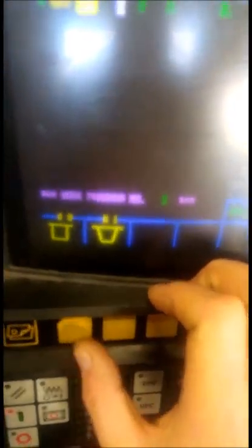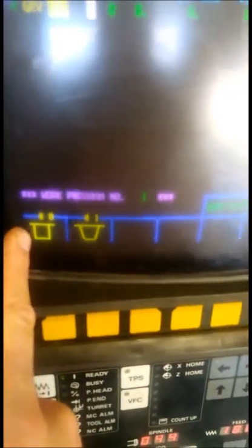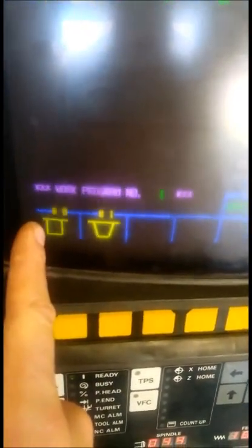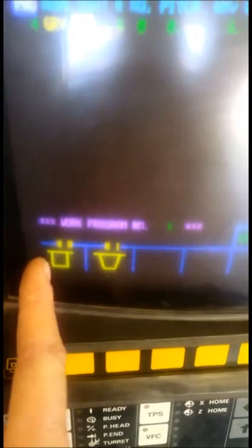So a 0 measures from that left-hand side of the tool. So if you're parting off a piece and you want to part it off to 10 mil, you've got to add on the width of your grooving tool. So I'd have to call that 13 mil. Whereas with this one, it measures from the other side. So I always use that one.